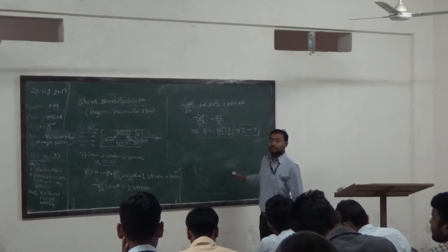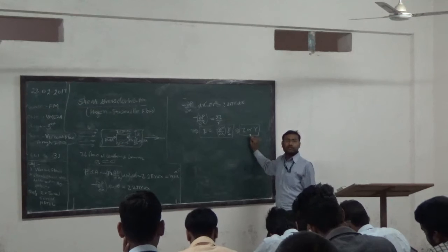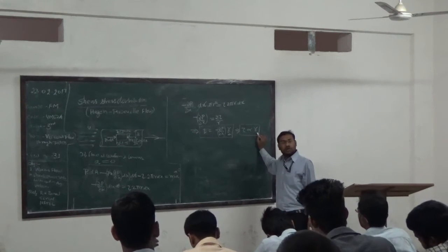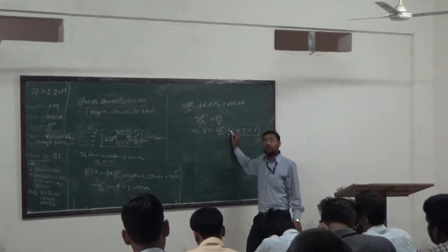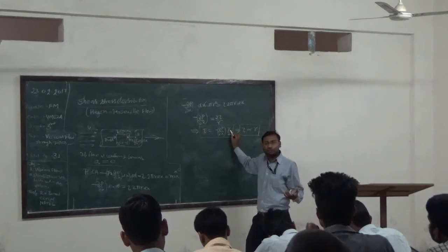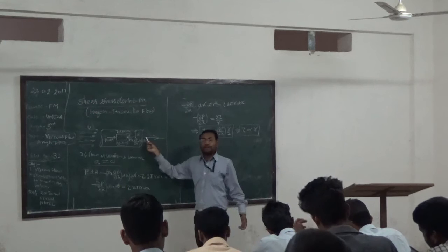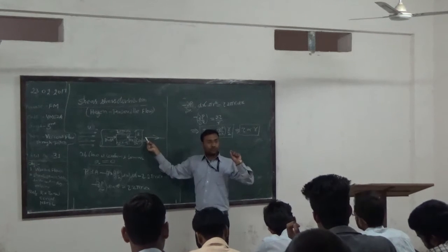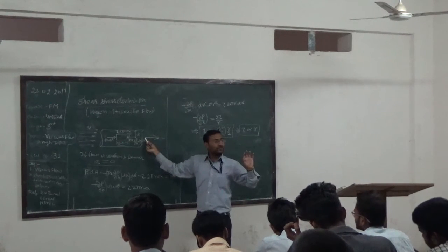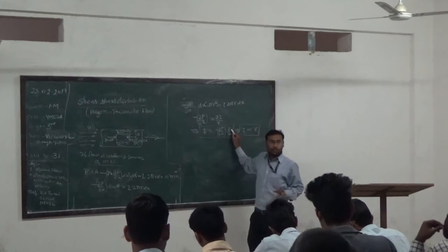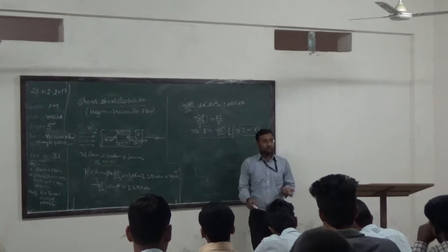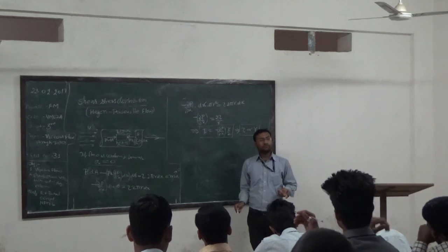Now from this, you can write that tau is directly proportional to r. Just substitute the value of r equal to 0. Small r equal to 0 means the center of the pipe. So when r is equal to 0, the shear stress will become 0.